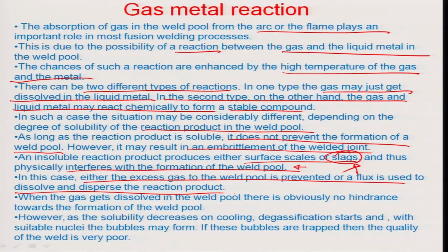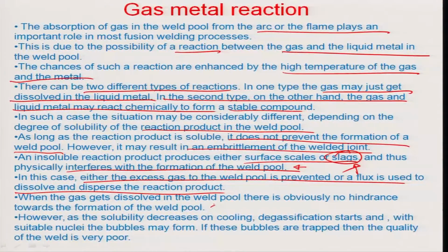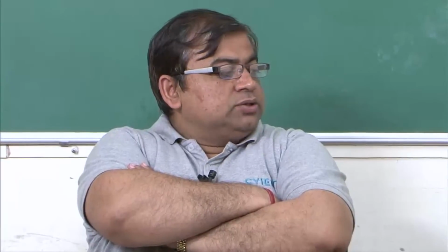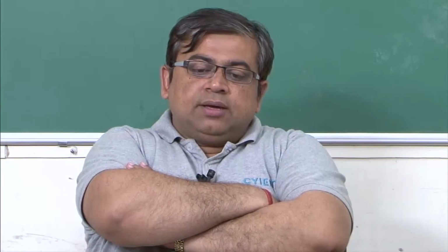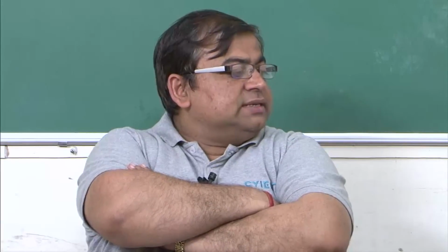When a gas gets dissolved in the weld pool, there is obviously no hindrance towards the formation of the weld pool. However, as the solubility decreases on cooling, degasification starts, and with suitable nuclei the bubbles may form. If these bubbles are trapped, then the quality of the weld becomes very poor. Even otherwise, the degasification may make the joint very porous, and this defect is very common in metals whose oxides are easily reducible by hydrogen, and can be avoided by adding a suitable deoxidant in the filler material which takes care of such oxides.